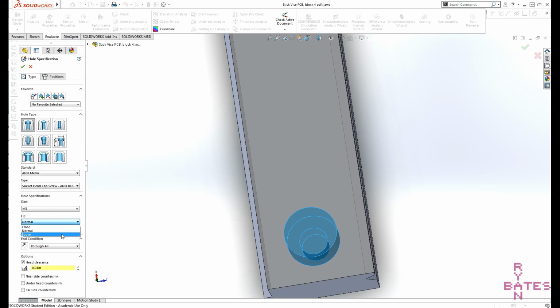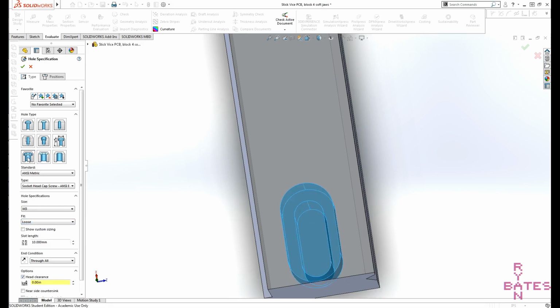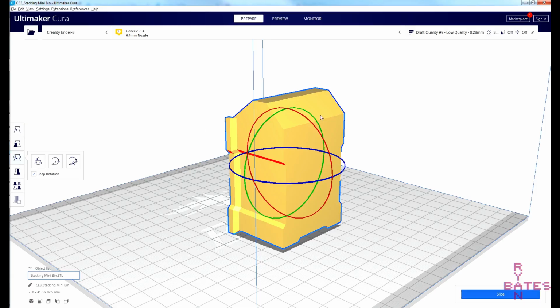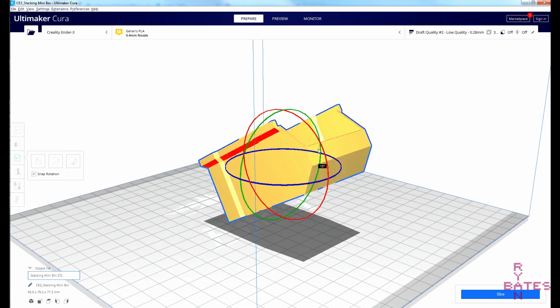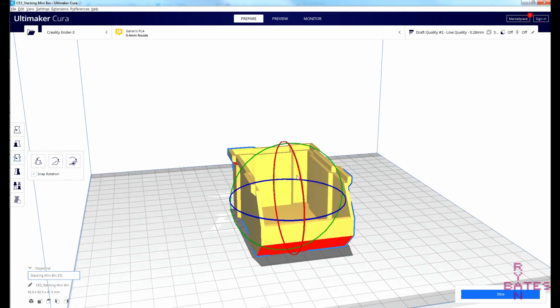In general, a good design principle is knowing what manufacturing technology you're going to use to create your part. With 3D printing, it's good to have relaxed tolerances where applicable, or, for example, using slots instead of holes when you're mating two parts. Orientation is one of the most important aspects of 3D printing. Orientation determines the strength of your printed part along with the overall probability of a successful print.